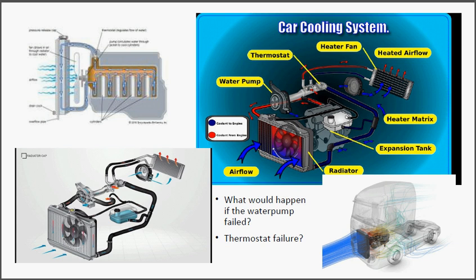Ideally, what you should do is get a remote temperature sensor, and you could check the surface of the pipes. That would do the trick as well, so you don't need to use your hands. If it's really, really hot, you can scald yourself. So make sure the engine is cooled down sufficiently before you attempt this check, and make sure the engine is turned off as well. It's very, very important.